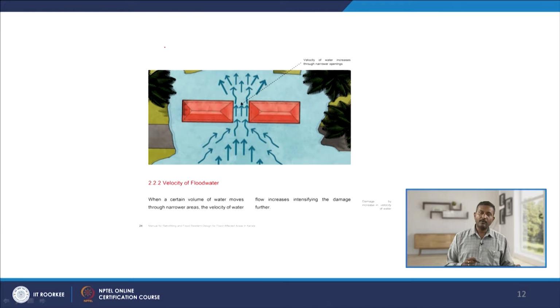Also the velocity of the flood water matters, because, as the other manual on the tsunami talks about, the moment you make row houses like this, that is where it is going to intensify the pressure, because it is a kind of bottleneck process. So the water affects this whole damage process, both the walls and the foundations. These are a few glimpses of the reasons, but there are many others which he has explained in his manual. And in fact, how to retrofit these things, because there are some solutions, not only the causes, but you also have to talk about the solutions.